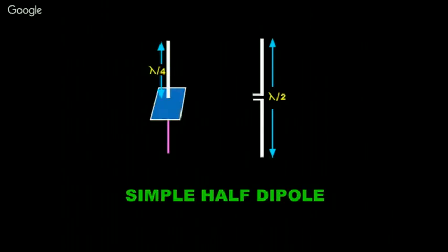But if you go on increasing the frequency, the size of dipole goes on decreasing. When you go up to TV, means 61 to 67 megahertz, it is around 1.5 meter. If you go to band 3, 170 to 230 megahertz, it comes less than half meter. So as you go on increasing the frequency, dipole size is going to decrease according to the frequency.